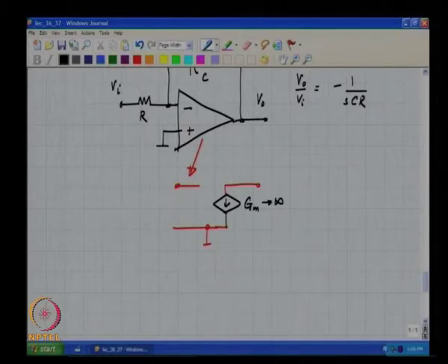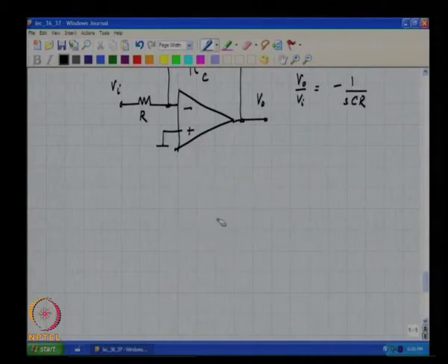The advantage of this, as I said, is that it does not have the problem of losing voltage swing because you need a voltage controlled voltage source in the form of a source follower inside.